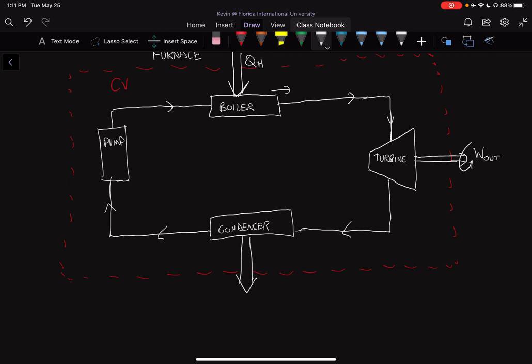It's the same as a heat exchanger, where we have our QL out, and our QL out is usually going to a low temperature sink, which is a river. Okay, so that's why most power plants are in a river usually, or close to a river. And following that, once the liquid is cold again, we run it through a pump, we increase the pressure, and we bring it back to the boiler where it boils, and then it starts the process all over again.